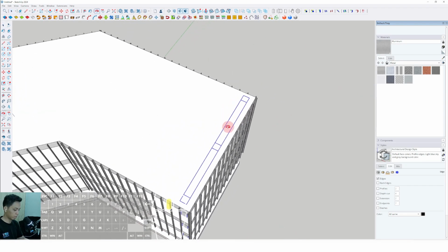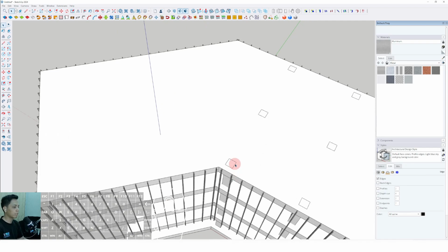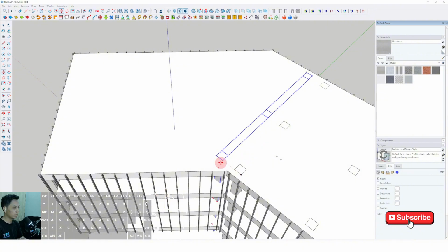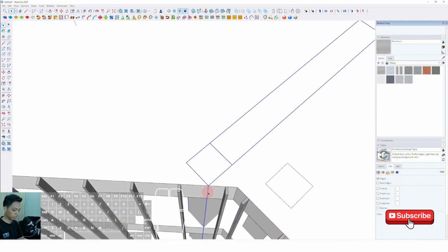Now we can select move, press Ctrl, then place this in another position, click, then we can type 2 slash and enter. Now we can select move. We can rotate it by following the building orientation in this position.